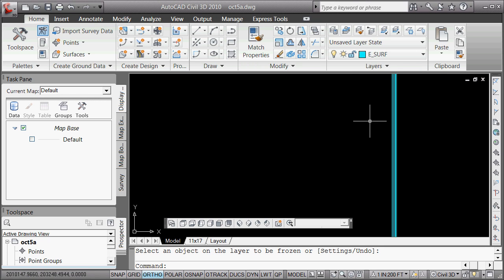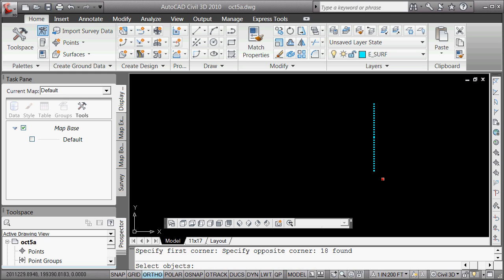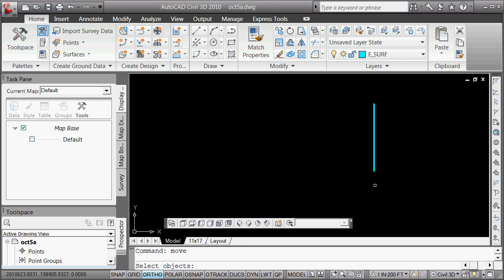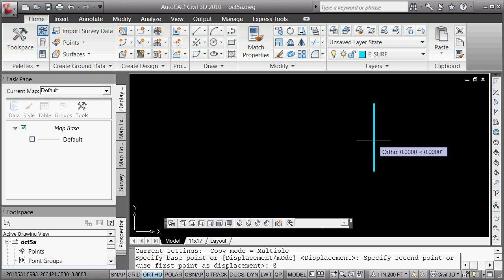All right. So now what I've got here is a set of lines that I need to move over to the right, 5280. So let me just do it. Move, cross, the more standard way, from click, at 5280, angle 0. I forgot to do a copy. So move, cross, copy. Sorry, doing copy. Cross, click, any point, then at 5280, angle 0.